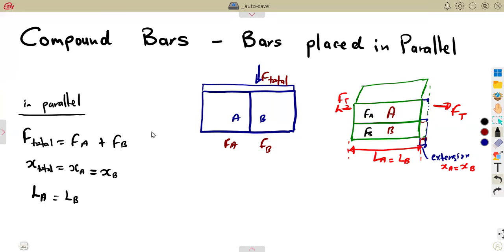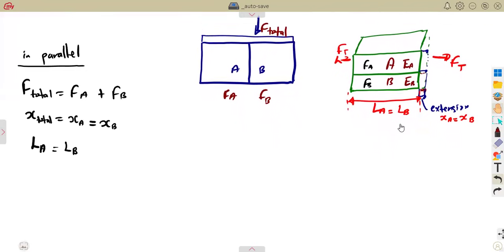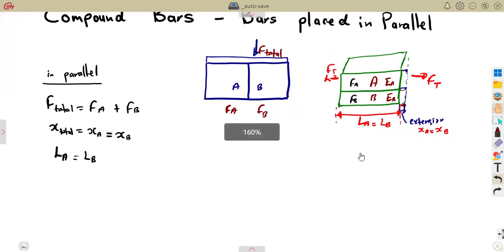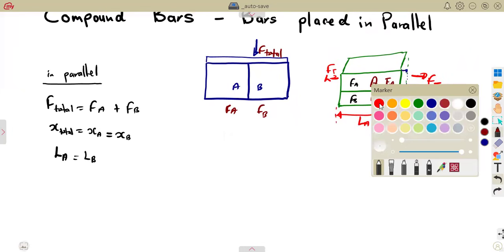So with this, we are going to have different values of the Young's modulus of elasticity. At A, they are going to give you the Young's modulus. At B, they are also going to give you the Young's modulus. But with these two, remember, the change in length is the same. So you just want to make some adjustments on this formula. This is what they will give you, and with that, you are the one who is to make adjustments. Out of these formulas, what adjustments can be made?